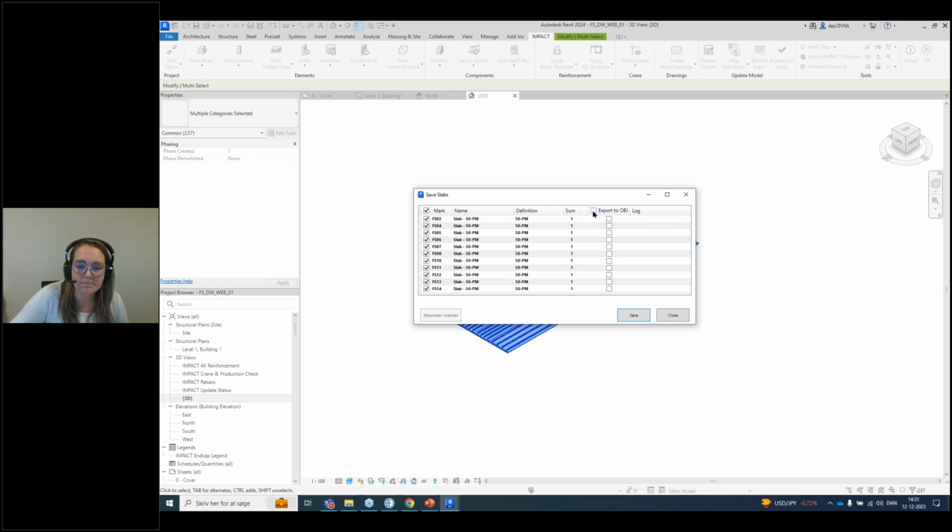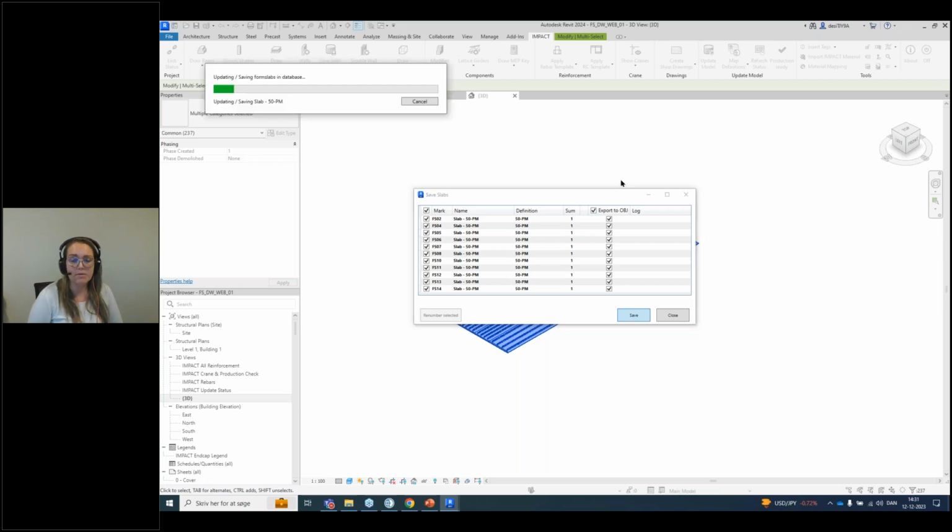While I'm saving them, you can just save them like this, or you can also add an OBJ file. An OBJ file is a very detailed recording of the geometry of the element. And this OBJ file I like to use when I preview the elements in Project Manager. So I'm gonna use that now, and while saving, I'm gonna do an IFC file, and I'm going to do an OBJ file export. An OBJ file is used when we're going to preview the elements later in Project Manager.